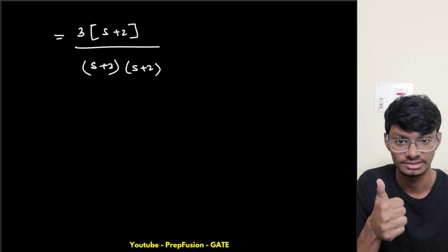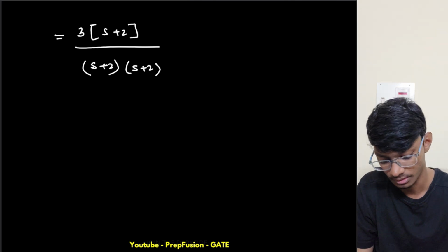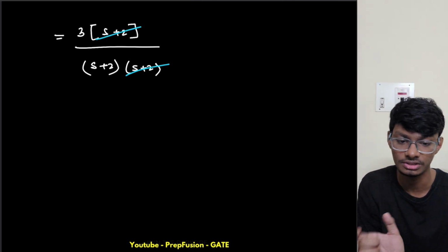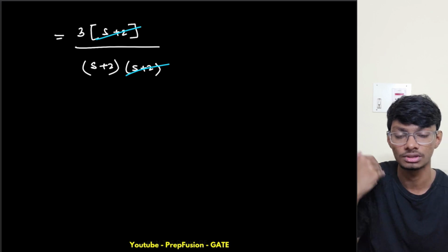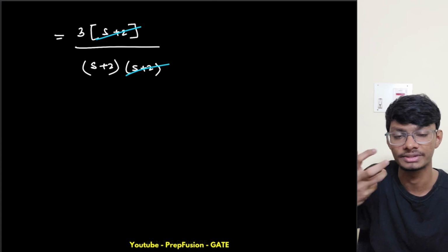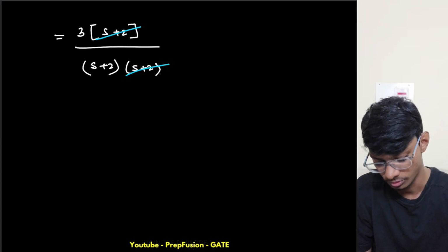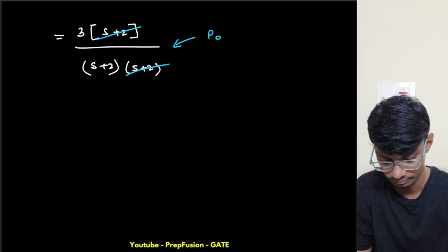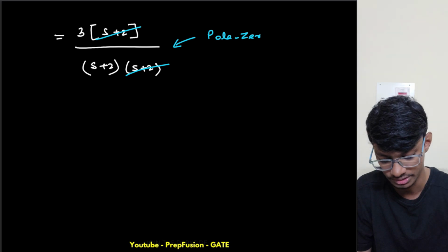Due to this pole zero cancellation, my state space representation won't be controllable, because it is not the canonical form. Basically we are not able to represent the system in the minimal form. I will write a few points about pole zero cancellation later also.